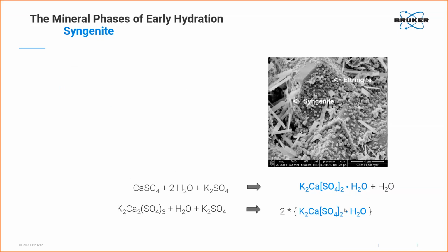So in any case, when we have available SO3, available alkali sulfates, and some moisture and water, this can lead to the reaction of syngenite. And as already said, due to the needle-like structure, there is some bonding in the particles, which may lead to some kind of framework. And of course, it can also lead to accelerated setting because the syngenite is taking out reactive SO3.